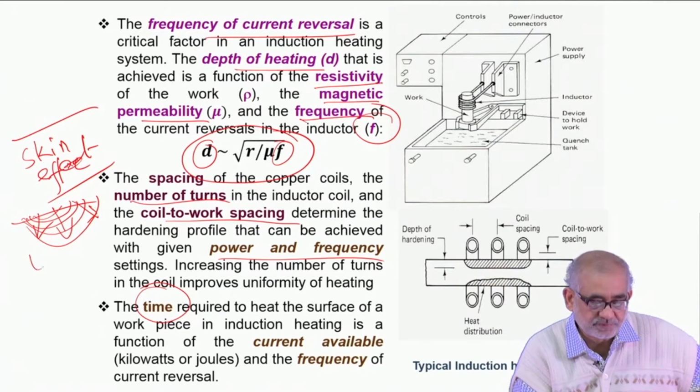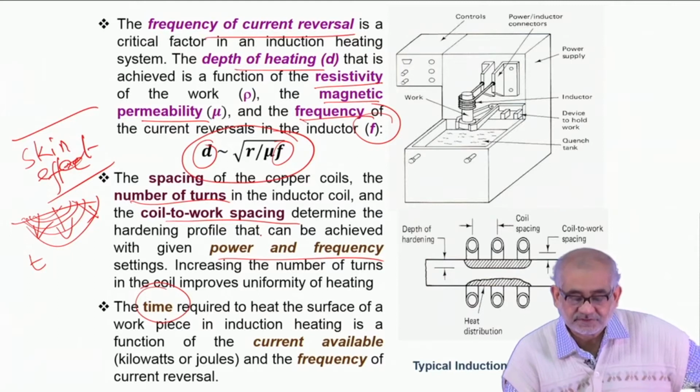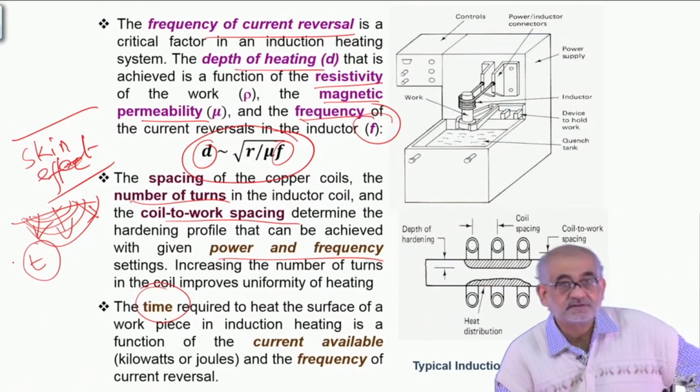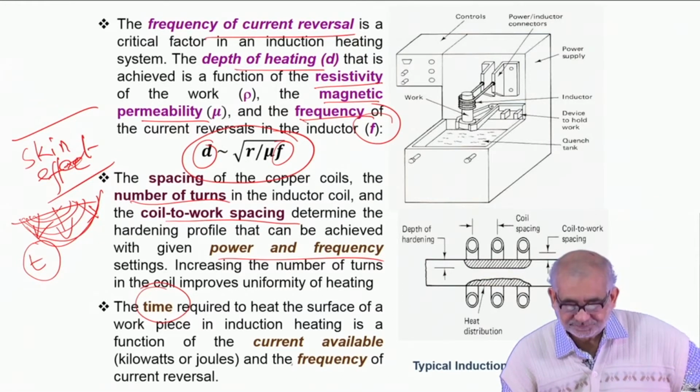So what is important is that we not only maintain the external parameters like frequency and the current and so on, we also apply such induction effect for a limited time, for a controlled time, so that the maximum temperature that we reach remains within the solid state and doesn't go into the liquid state.